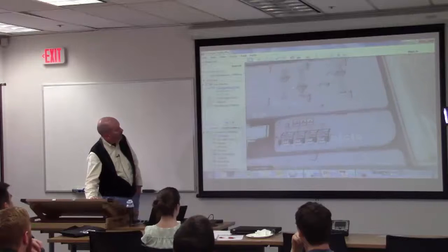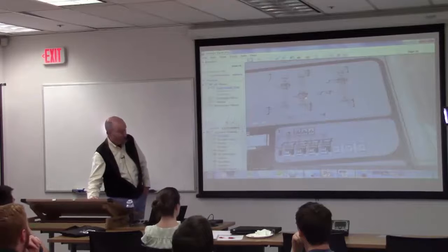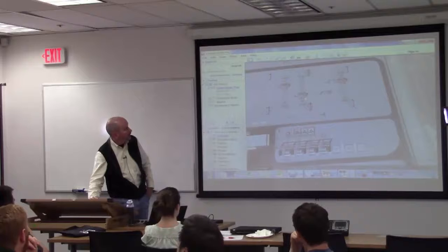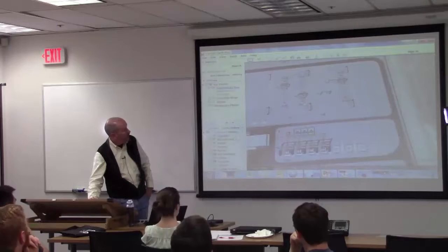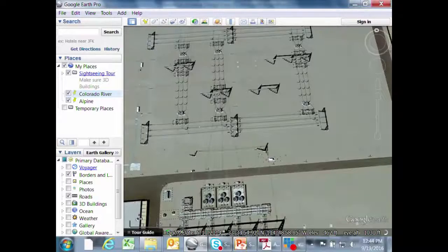Now then, let's look over on this side. This is a little 230 yard, and most of the time you don't think of 230 yards as being little, but in this case it is. The thing I'd like to point out is just these circuit breakers. Now, the way Edison does their circuit breaker foundations, and it's hard to see in this, I understand, is they just put a big slab down, and then they will use epoxy anchor bolts to actually bolt the circuit breaker down to the foundation.